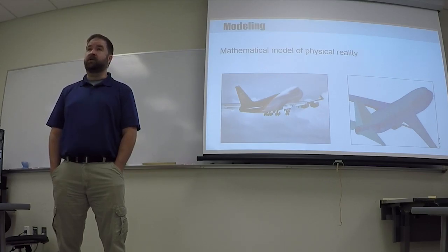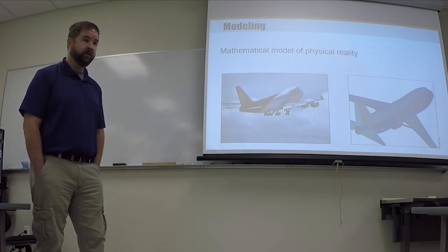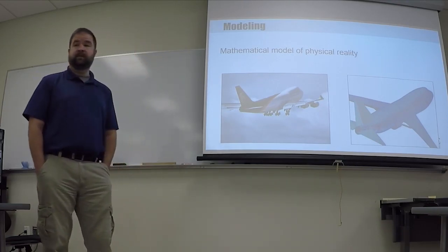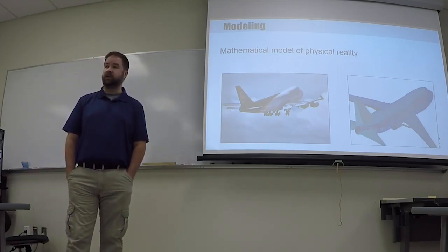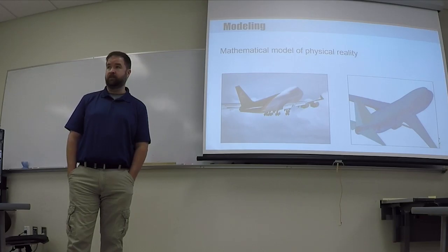So we're going to start today using bars and beams to represent structures. And we're going to keep it really, really, really ridiculously simple and see how well the solution matches the solution that it should have. That's the point, and that's why we're going to start with just beam elements instead of trying to model our structure as accurately as possible.